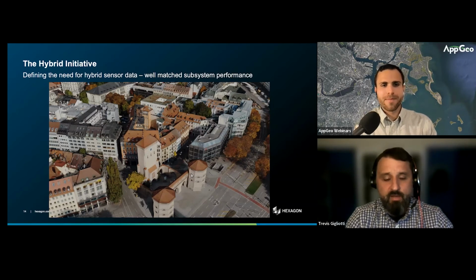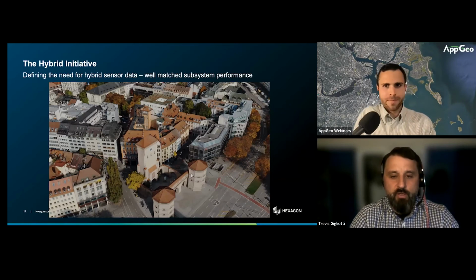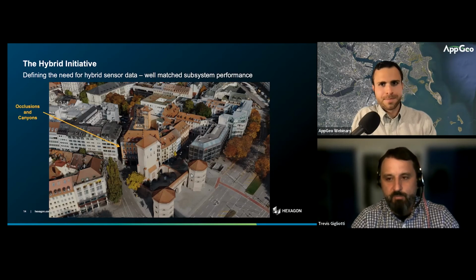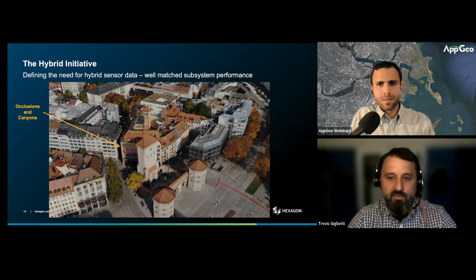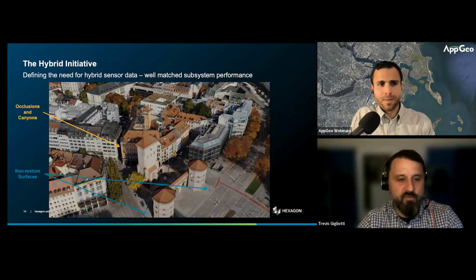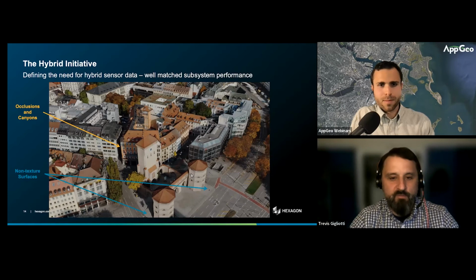Right. So with this slide, we want to illustrate the areas where traditional photogrammetry struggles and LiDAR takes over in our process by adding a bit more robustness to the data, right? We're really focused in MetroHD on getting the geometry right. And that's what the augmentation of the LiDAR sensor really allows us to do. So point clouds generated from imaging only, even if flown with very dense overlaps to facilitate dense matching, still have problem areas. And we're looking at some of those right here, occlusions and canyons. It's very difficult to get points on the surface or on the facades of buildings through traditional photogrammetry, where you're looking for the acquisition and matching of the stereo pair to generate that elevation information. In these tight areas that are often shadowed and geometry restricted, LiDAR can take over.